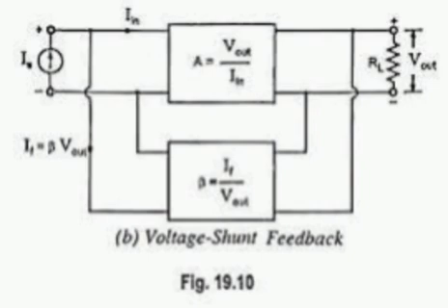AI equal to beta. In most of the circuits, this approximation can be used. Power gain AP equal to minus AV into AI. Load power PL equal VL square by RL equal to VPP square by 8 RL. PL means AC load power, VL means RMS load voltage, VPP means peak to peak load voltage, RL means load resistance. Transistor power dissipation, PDQ equal VCEQ into ICQ, where PDQ means quiescent power dissipation, VCEQ means quiescent collector emitter voltage, ICQ quiescent collector current.